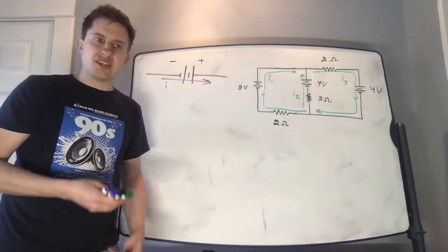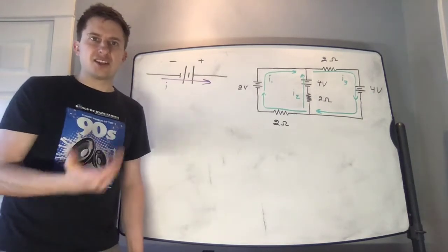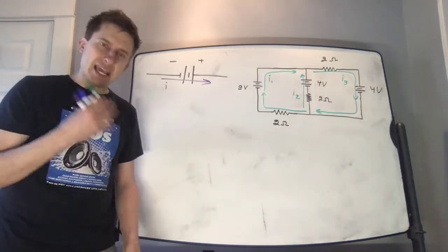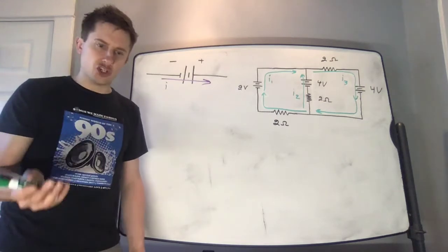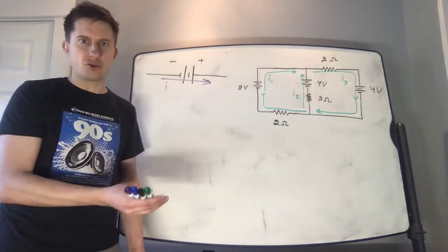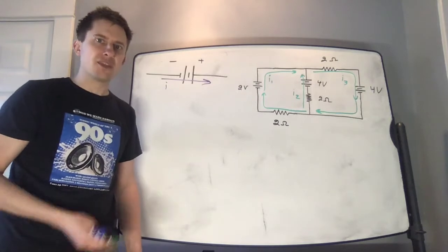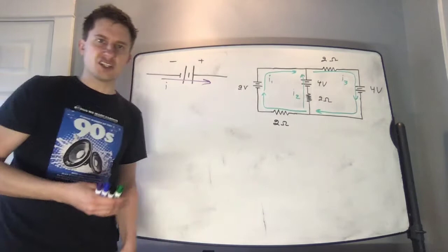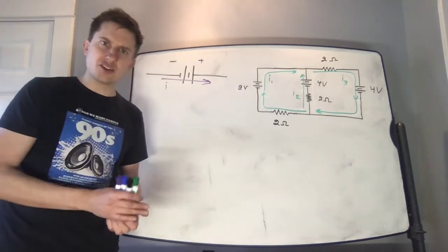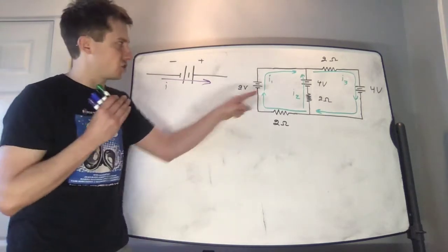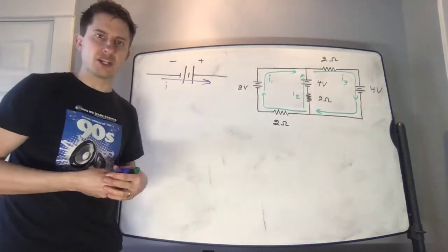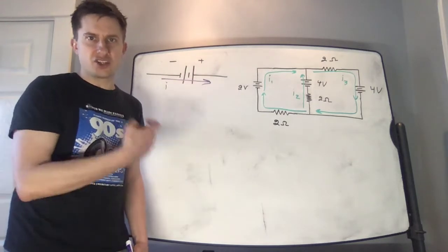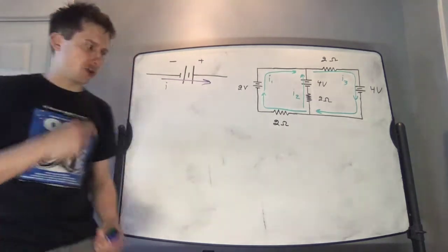However, as I said previously, it is okay to guess the direction that a current is flowing when you are applying Kirchhoff's laws. And if we guess wrong, that will just be shown when we solve for the unknown current and find a negative number. Therefore, it is okay if I guess wrong on the direction that the current is flowing through a circuit. So for an instructive example, I decided to choose the directions of the currents as shown here. So now we will look for all the junctions in this circuit and apply Kirchhoff's junction rule.